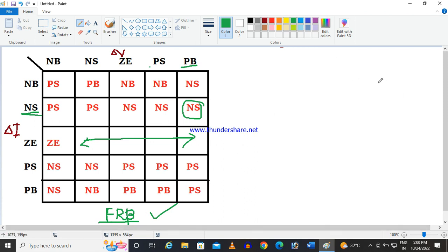So during the controller design, we have to take the feedback, means we have to take the voltage and current through an ADC. Then you take the product of that, which will give the instantaneous power. You take the difference of present power and the previous power, which will give you del P. Similarly, you take the difference of present voltage and previous voltage, which will give you del V. If you divide these two, it will give the change of current.